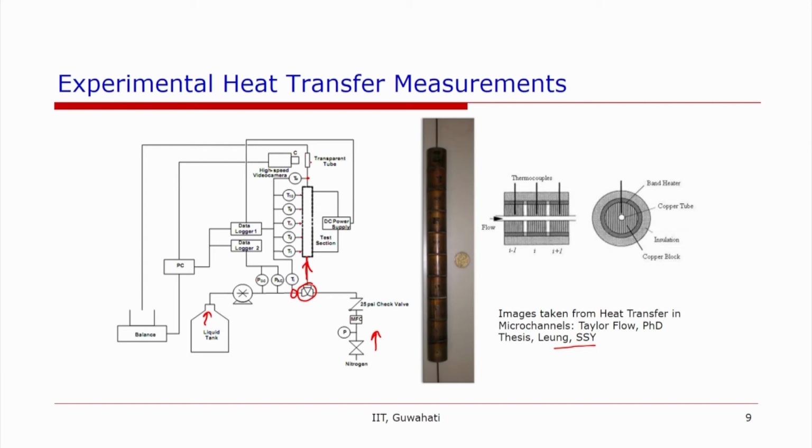They also have an arrangement for confirming the flow regime in the channel, and then the fluid is brought outside and released into the atmosphere. So, that is a typical experimental setup, and they have an H boundary condition in this case, and the wall temperature is being measured at different sections.